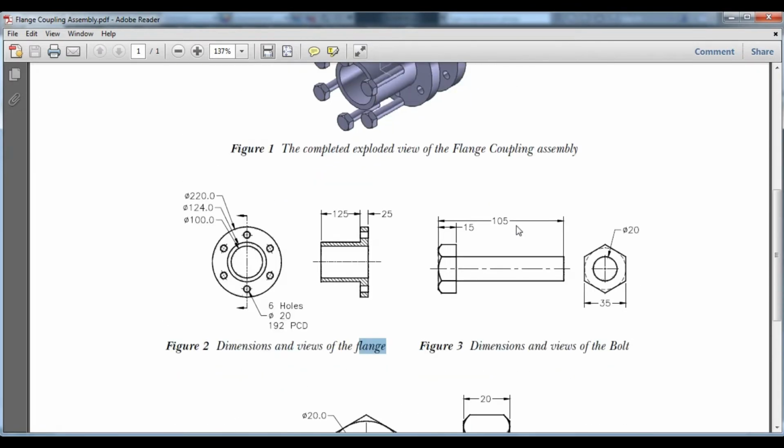Now, in the practice or tutorial on extrude and revolve, to draw the flange coupling, you can see in the tutorial part from the last video how to draw extrude and how to make revolve, which are 3D commands, where we explain what an extrude is and what a revolve is. For the flange coupling, we can draw it with the extrude command and also with the revolve command. The extrude command requires only a profile, and revolve requires a profile and an axis also.